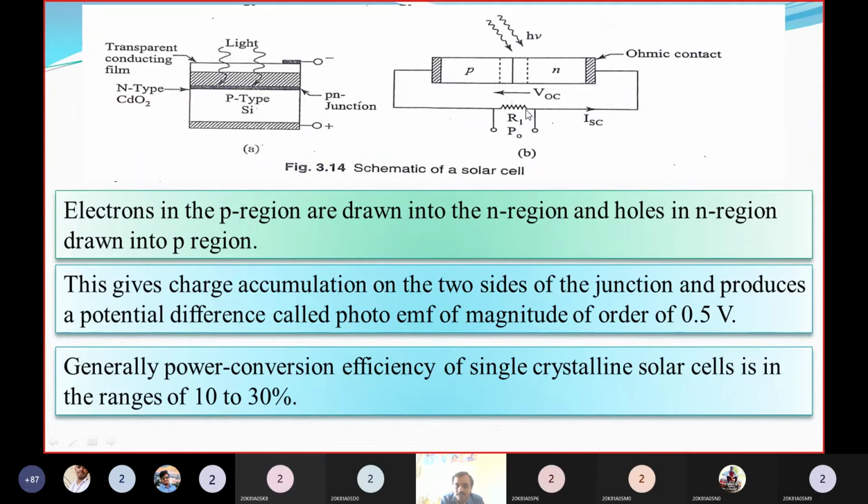So how to measure the short circuit current? There is a solar cell experiment for you as well. Just remove the load resistance and short these two terminals by connecting them.